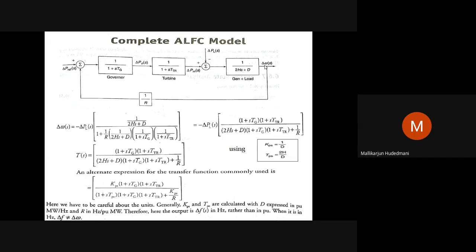This delta omega is to be addressed by the turbine by giving mechanical input to that. Then how can the turbine give a mechanical input to that? If it is controlled from its valve positions. How will the valve open to supply the additional input to the turbine? They require the governor to act. How does the governor act to displace the valve? It will get the correction at its input. How does the correction over here come? The feedback. See how the sequence is connected.